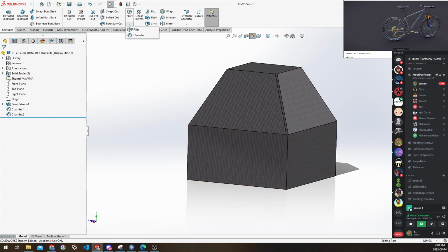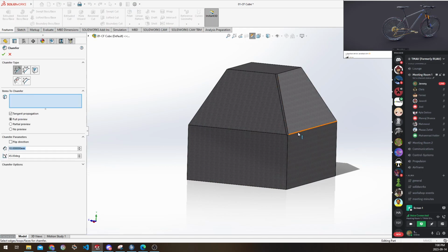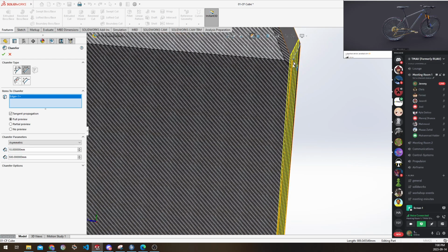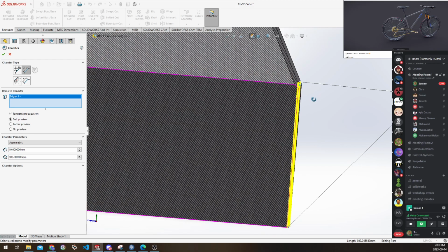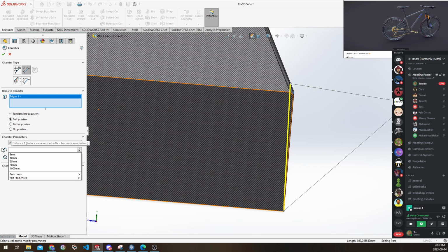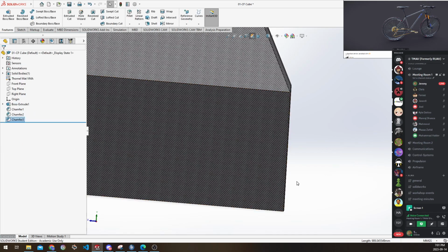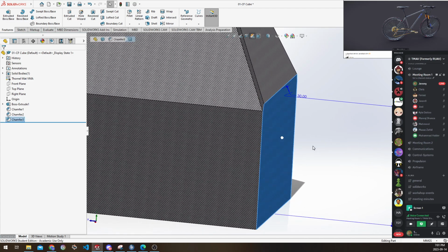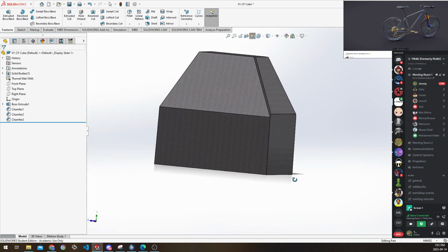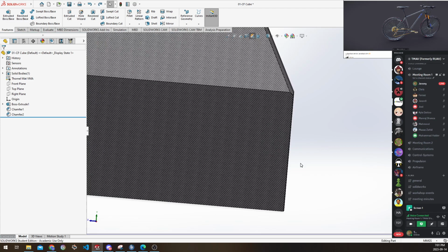So what we would do for that is we would take a chamfer, an asymmetric chamfer on this corner. This one we want to be 500 because it needs to go all the way down. And then we would take that in, and we just want an ever so slight angle. Typically, I think the industry standard is about 3 degrees. So maybe let's make this like 20, 30. I don't know exactly what would be 3 degrees. Not really relevant to calculate it, but you would want to do the calculation if you were doing it. And so see now, this is no longer 90 degrees, but it's off by a little bit. This would be much more mass manufacturable of a part now. Okay, so I'm going to back that off.